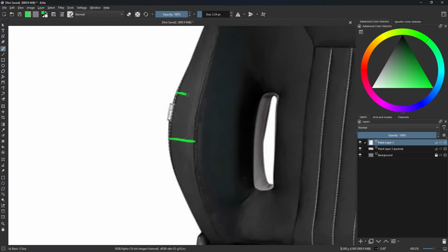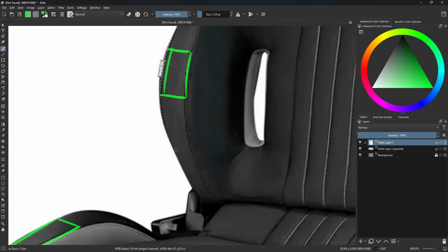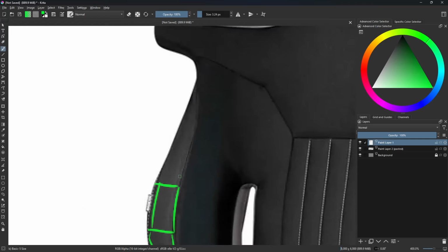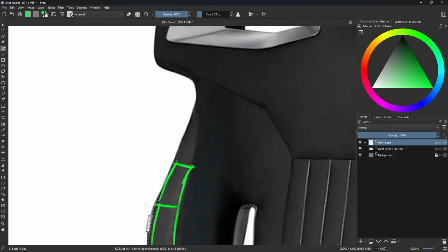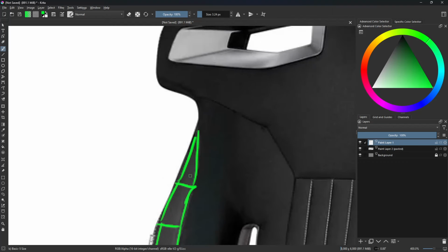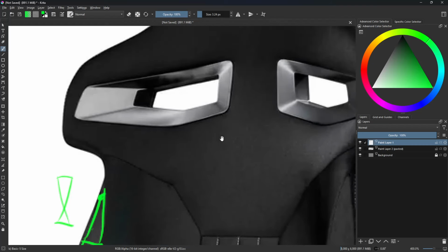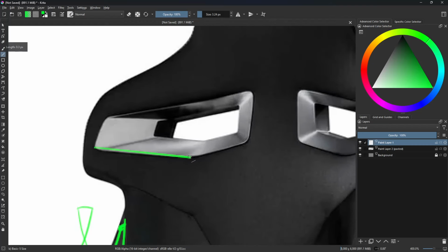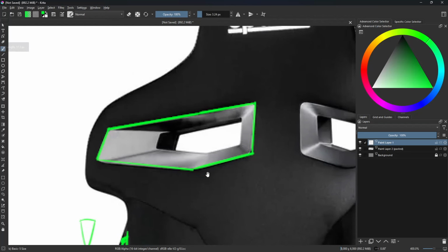You're just breaking them down in your head on how you're going to make them, how many edges you might need. You don't have to draw them out like this either. You just start looking at them and thinking, where are these edges going to go? Like you might have to make a quad that folds in over on itself, doing something like that almost right there. You're identifying shapes like this. You're not worrying about those small bevels, all right? You're just worrying about the big overall shapes first. This is your blockout mesh, more or less, when you start modeling.